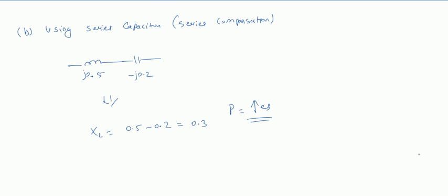Third thing for reducing the value of XL is using bundle conductor. Using bundled conductor, we can reduce the value of XL and have a greater value of power transfer. So what happens in bundle conductor, we will see in detail in the part on parameters of the transmission line, in that we will see how to find the value of inductance and the capacitance of the transmission line.